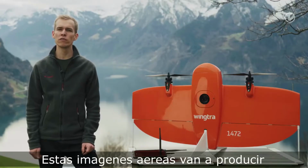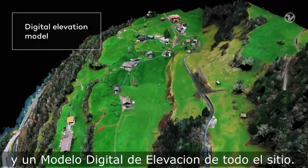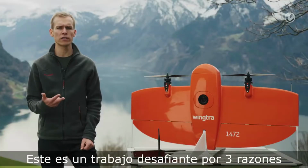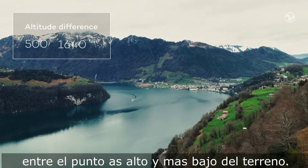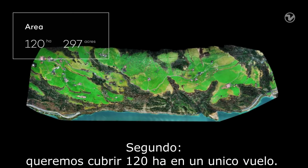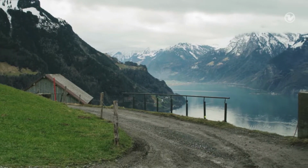With the aerial images we will produce an orthomosaic map, a point cloud and a digital elevation model of the site. This is a challenging job for three reasons. First, there is a high altitude difference of 500 meters between the highest and the lowest point in the map. Second, we want to cover 120 hectares in only one flight. And third, we have to take off on a confined space on this small road.